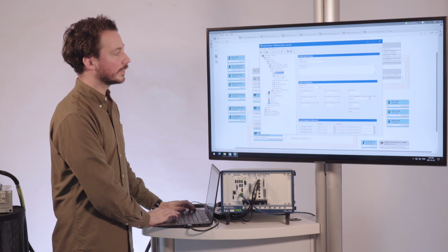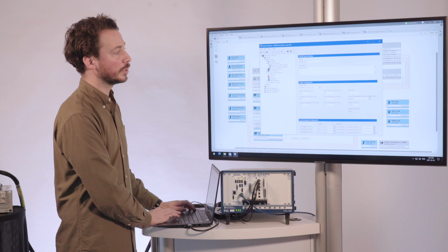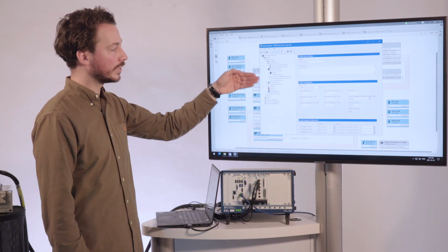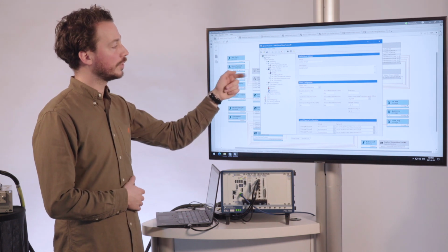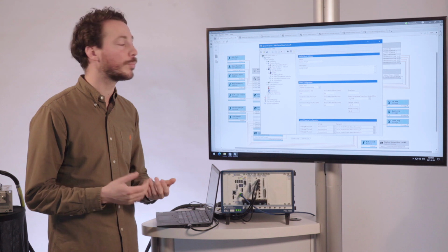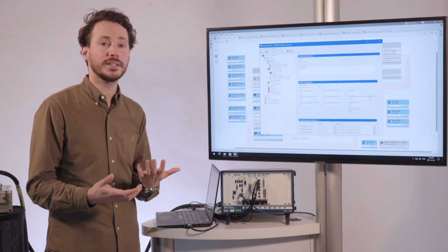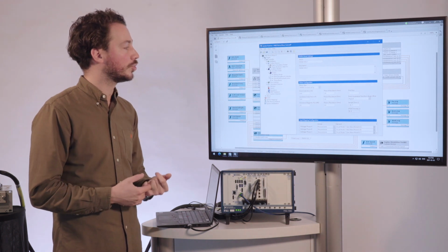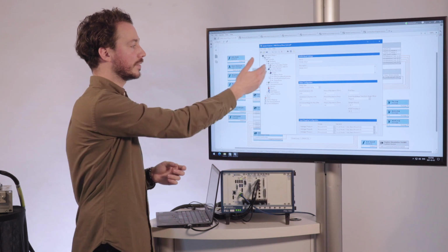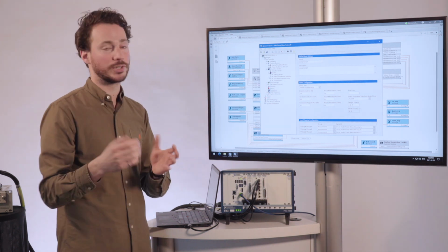The last thing that I'd like to show you is this part, because it's extremely important for this demonstration: the simulation models. So under simulation models, you can see here we have 4 different models. There's the battery model, there's the boost controller, the FOC, and we have actually a function for a torque ramp. So these are 4 models that we've developed outside of VeriStand in Simulink, and we've then compiled them to a Linux executable file that we then import into this model, and this is how we can map that actual battery model connected eventually to the rest of this system.